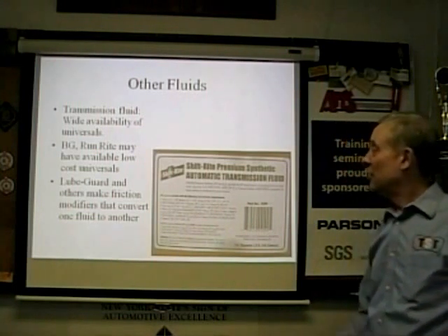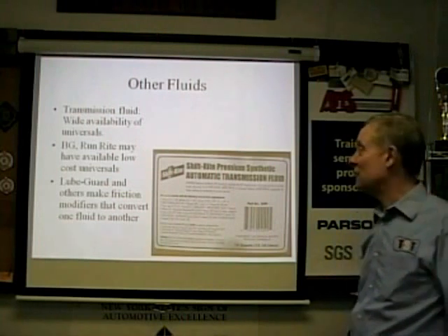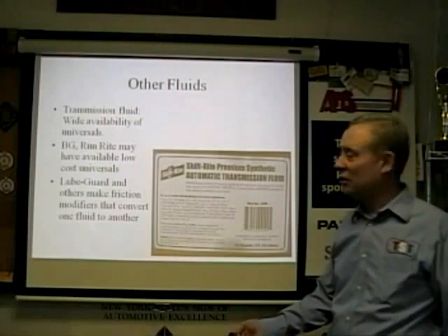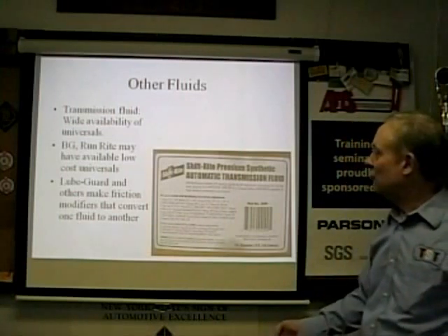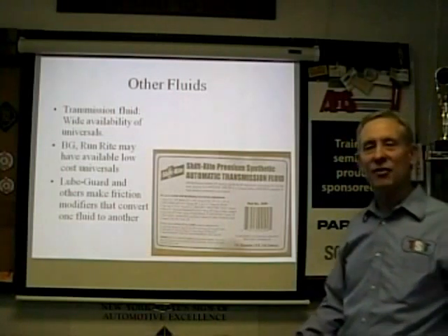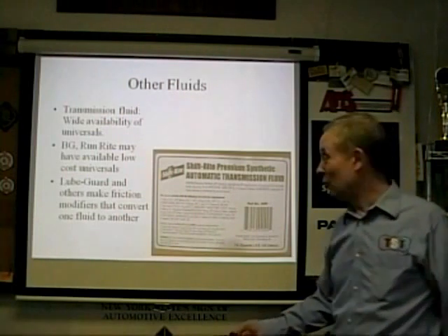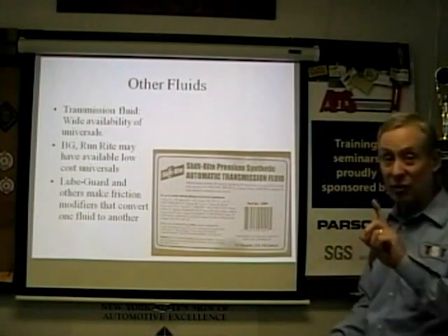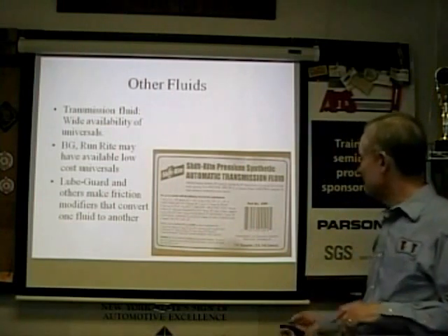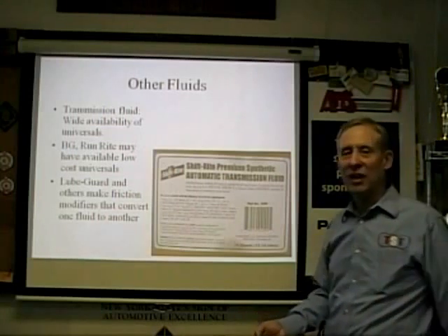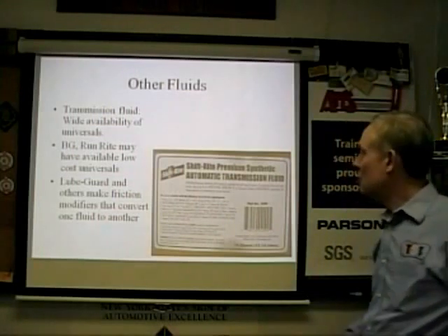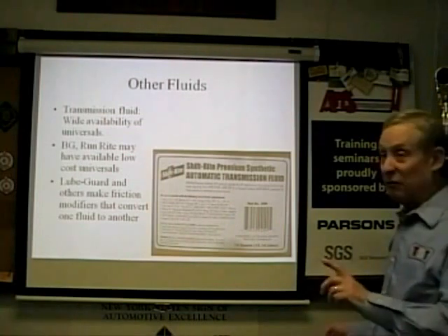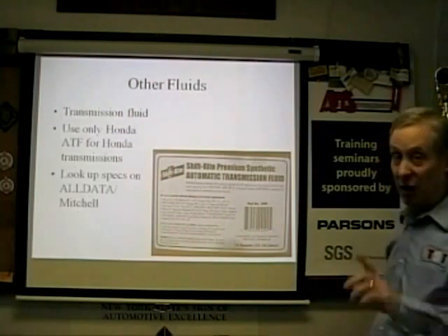That said, BG and Run Right have low-cost universals, and I actually like a lot of the chemistry these companies have. LubeGuard is well known in the industry. They have tremendous additives, and pretty much every transmission guy I know likes LubeGuard products, but there are different LubeGuard products. So you have to make sure you're using the right one for your application. Someone like Wayne Colonna at ATSG will tell you to use the correct LubeGuard by using their chart. With the correct fluid, it works great. But be careful.